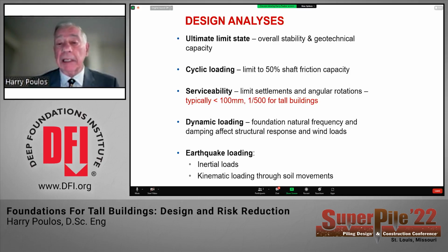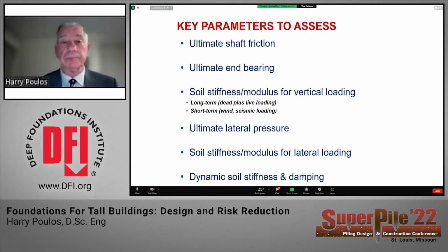With respect to dynamic loading, that's an important issue, not only because of human comfort, but because the foundation natural frequency and the damping also affect the structural response and actually the wind loading. And with respect to earthquake loading, as I mentioned before, we have to look at two components. One is the inertial loads that the structure imposes on the foundation, and the other is kinematic loading, which is induced into the foundation system because the ground moves during a seismic event.